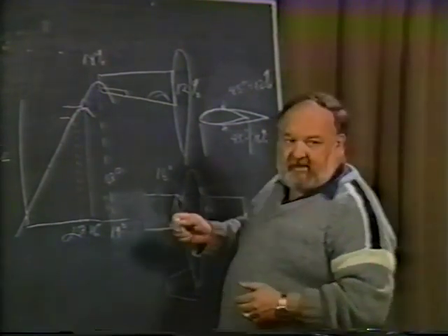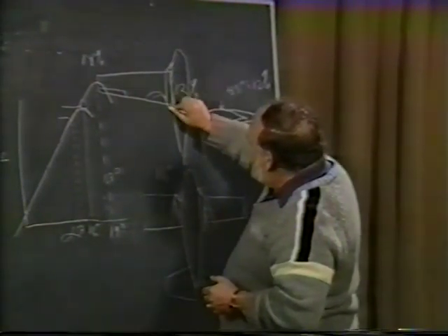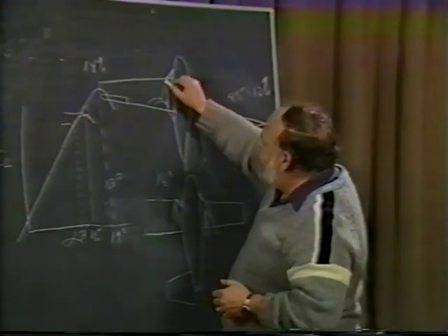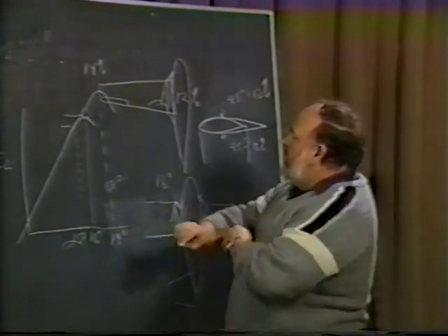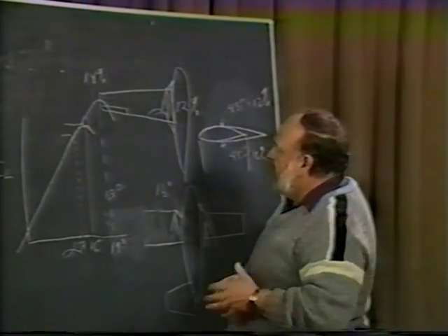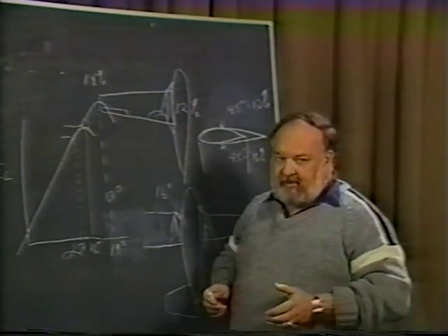Now one of the other things we did on the Bede 5, some of you might remember, is that we actually used a fillet in here that had a swept forward leading edge to it. So we helped trigger off the stall by the swept leading edge, by the thicker airfoil out at the tip, and the end result is you can have an extremely good flying airplane.